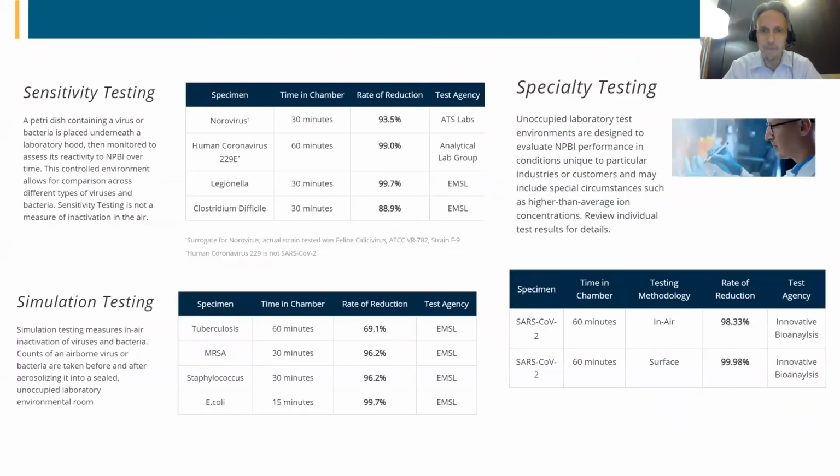As well, though, because I've imparted an energy potential, an electrical potential to the atoms and molecules in the air that go out into the space and work on the particles of concern in the space itself. If there are certain viruses or pathogens in the space that can be inactivated or killed through an electrostatic interaction with the cell surface of that particular pathogen, needlepoint bipolar ionization has been proven to be effective at inactivating and killing certain viruses and pathogens based on certain ion concentrations, certain amounts of time, at a specific rate of reduction.